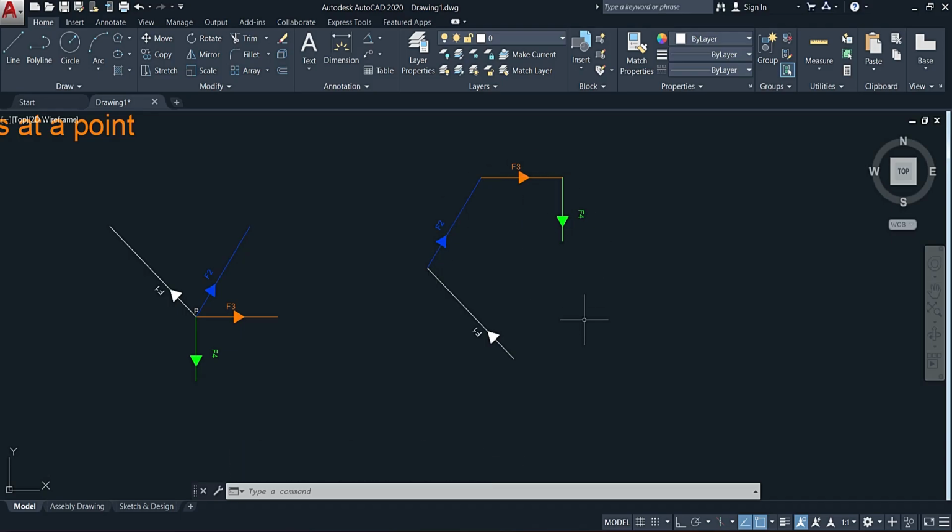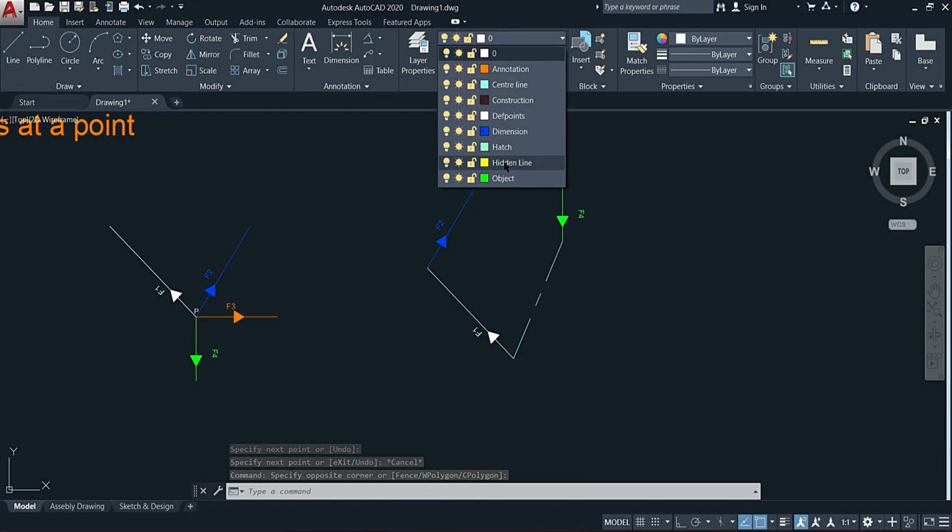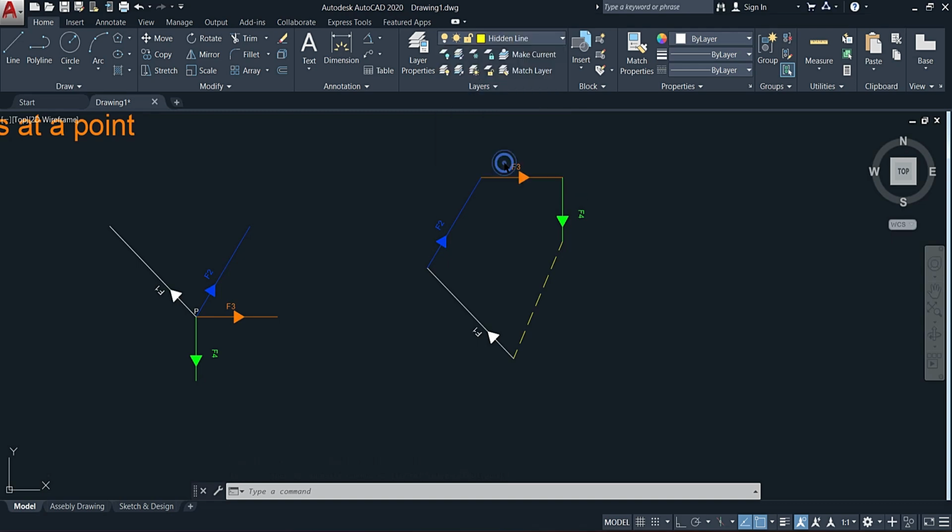All right, now this force polygon is incomplete. It's not a sealed or closed polygon. Now this is where we close things off. How do we do this? We simply draw a line from the end of force 4 to the tail of force 1. Now this line here, and I'm going to switch things around and change the line type to that broken line there. All right. Now the direction that this force is acting in is that it's acting along this direction here.